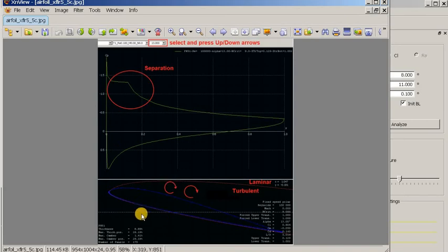So once again we have this airfoil, we have the separation of the flow, we have the turbulent region, so we have the boundary layer defined by the red line, with the turbulent region behind this line and laminar flow above this line. And we also know that because of this huge boundary layer, in the simplest terms, we have the effective profile of this airfoil different, following the boundary layer, and so the drag is high as well.